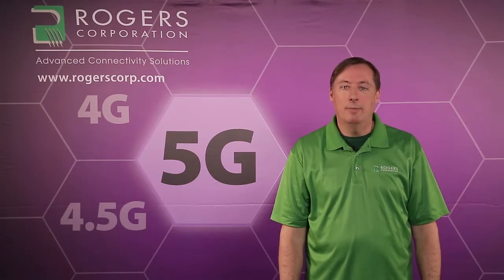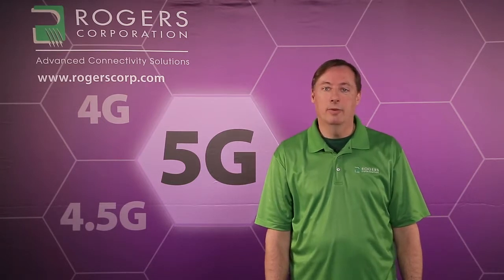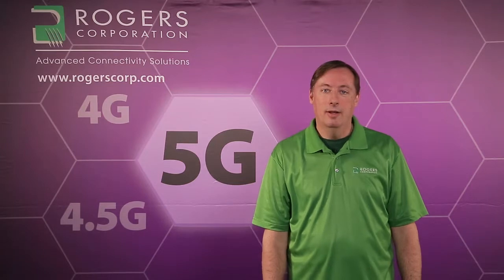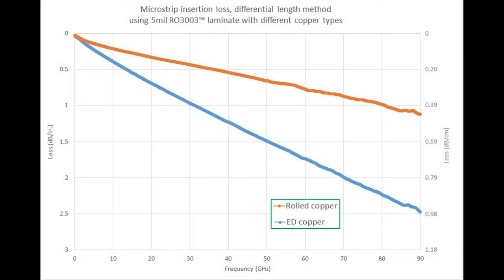The impact of copper surface roughness on insertion loss is also thickness dependent, and what I mean by that is substrate thickness dependent. So a thinner circuit is more dominated by the conductor effects than a thicker circuit. And this is shown in the following picture. In this graph I'm showing insertion loss comparisons using the exact same material. It's 5 mil RO3003 material, and I'm using copper of different roughness.